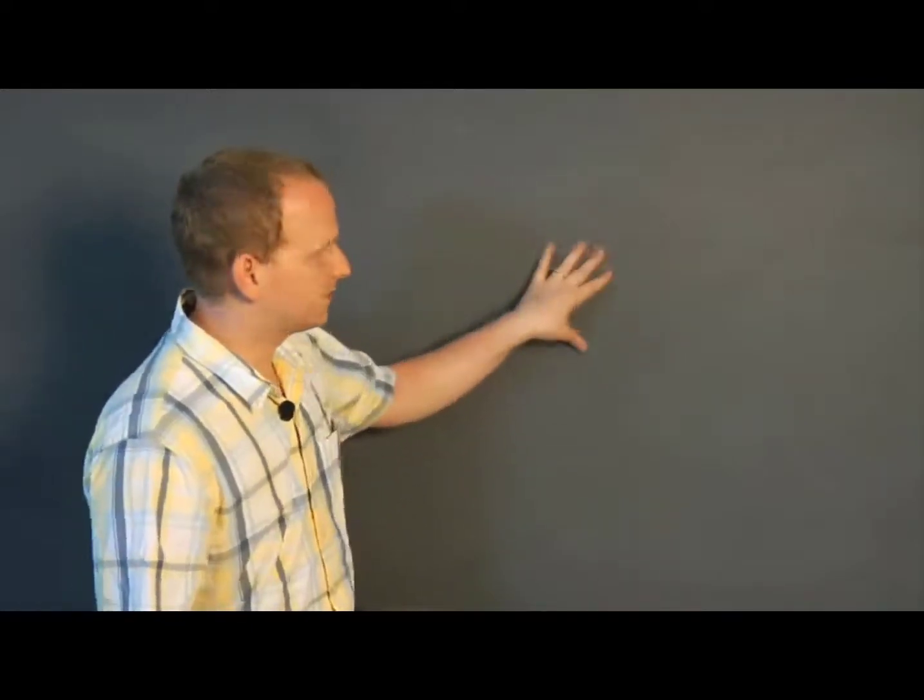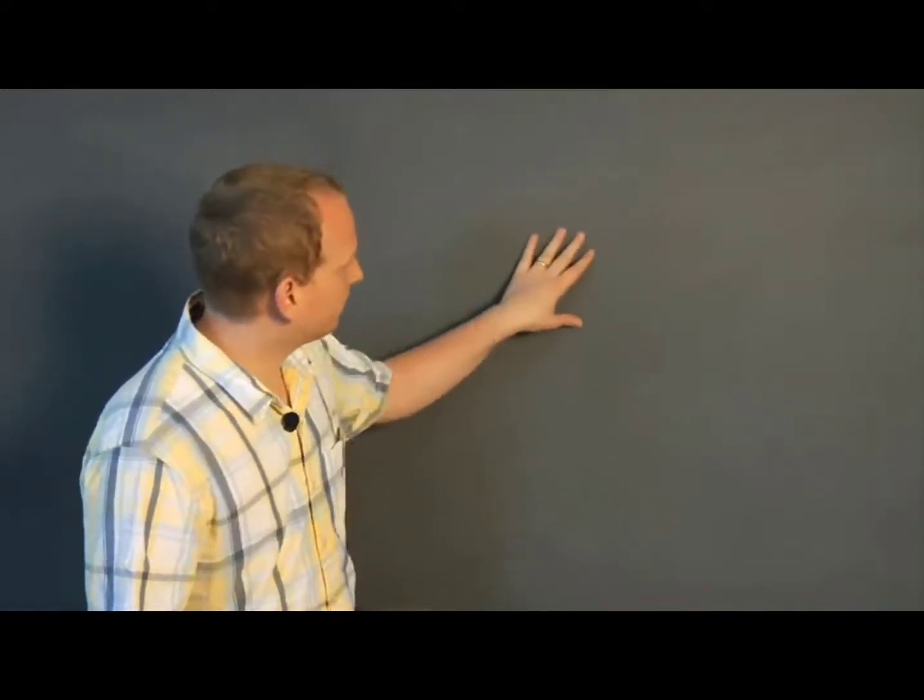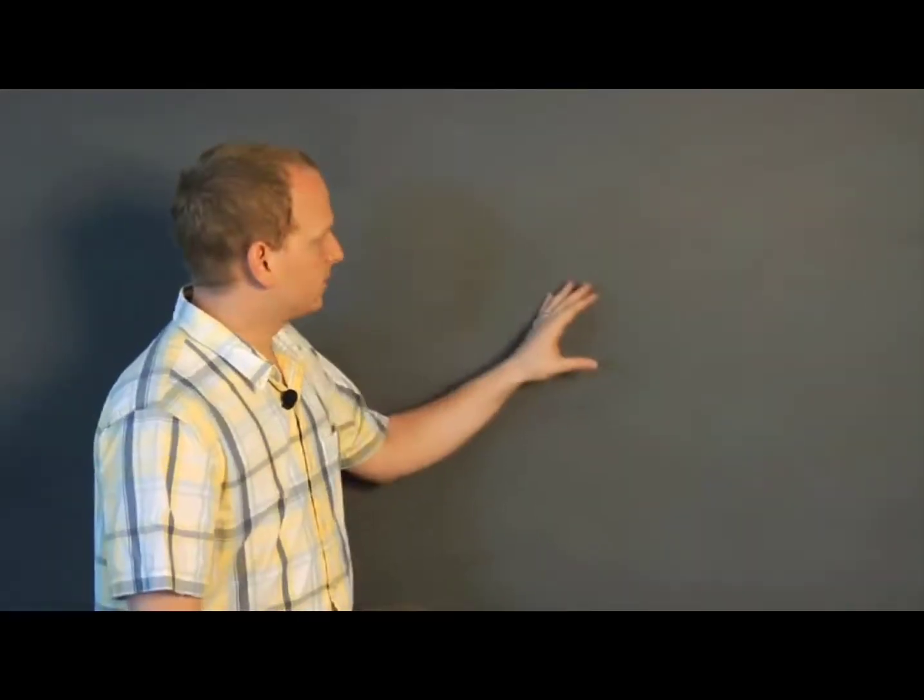And here we have the sandblasted finish. It's similar to the honed finish as far as the looks go, but when you feel it, it's a little bit more rough. It's not as smooth. The way this surface finish is created is by shooting a stream of sand onto the surface, which blasts away little particles of the stone.